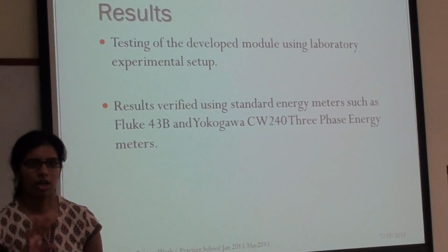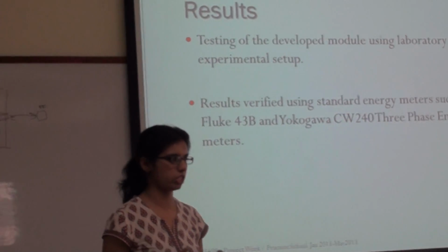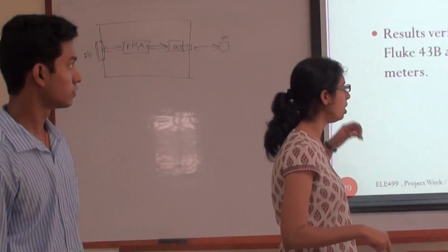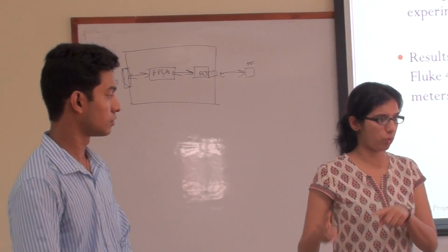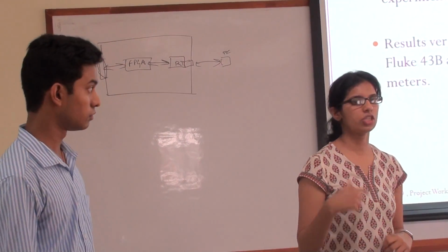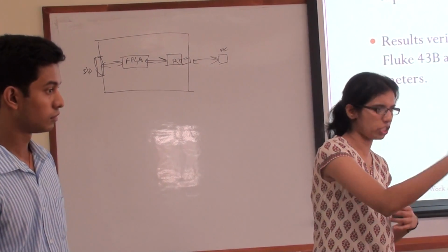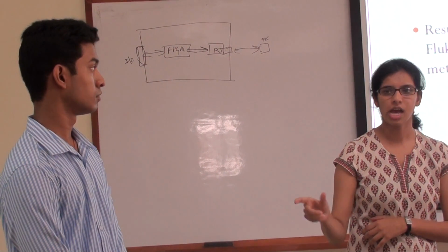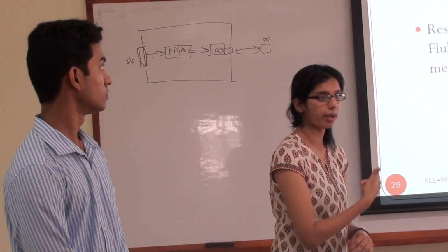So, like I said, there are three parts to it. First is the power, the voltage and current measurement. The second one is the event detection, that's sag and swell. And the third part is the event logging. You're just trying to log the data that you sent so that you can use it for future reference. That's the data storage part of it, and that comes under the event logging part.